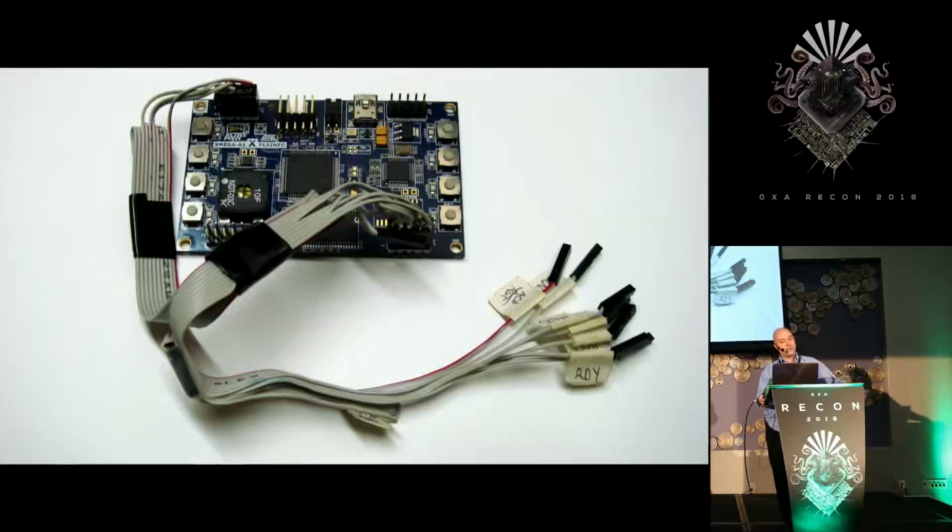To monitor the data passed between the set-top box main controller and the ACP on the SPI bus, I use an Atmel XMega development board. I configured 2 SPI ports as slave, with the master out slave in signal connected to one, and master in slave out signal connected to the master out slave in input of the second port. So from one port, I get bytes that are sent from the set-top box controller. From the other port, I get the bytes sent from the ACP.